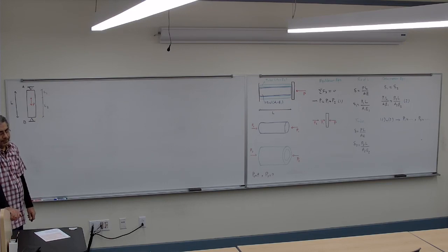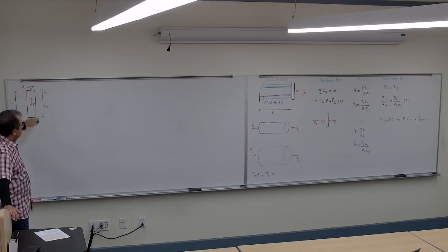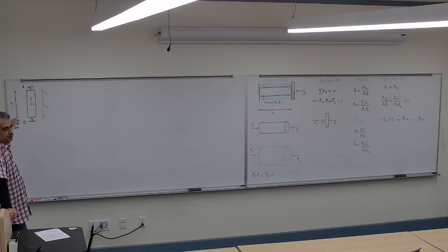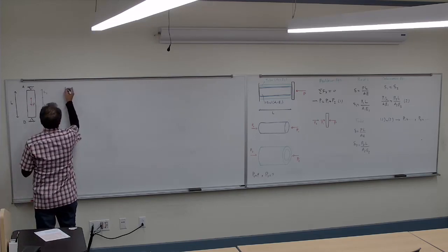Right. So if you look at that, I have two unknowns here, two unknowns there. Two reactions there, so 4 reactions. And because there is no force in the X direction, the X reaction we don't care about. It's only going to be the Y reaction. So if I redraw that, what I'm going to get is this.